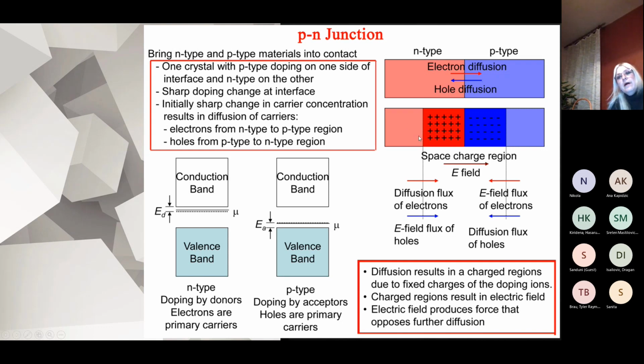So now quite a large number of electrons from the N-type region, which moved into the P-type region, because of the built electric field now want to come back to the positive side. Also the holes which moved to the N-type region, because of the built electric field, will want to return in the opposite direction.